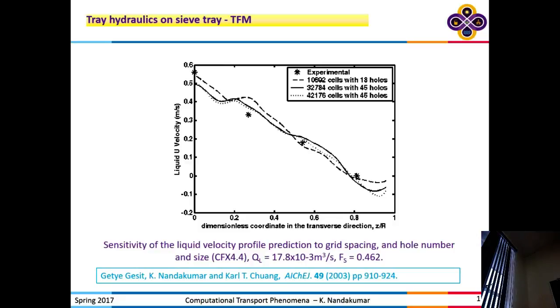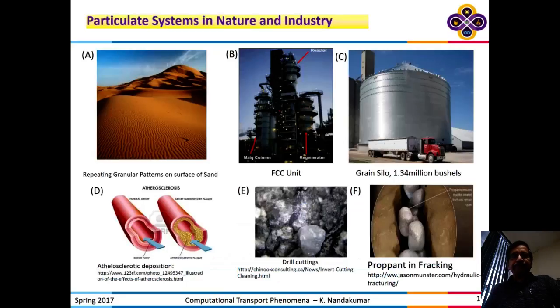Right? So that's an encouraging result, that these models are adequate to predict the velocity variation, including the variation here. I guess the zero line is here. So if you extrapolate it all the way, that shows that there are some negative velocities. Imagine if you have a curved surface, near the end, it's possible that you have reverse flows. Okay? And that's being captured in that simulation. So we have been talking about the types of challenges, using distillation as an example, how one can go about answering some of those questions without any detail.